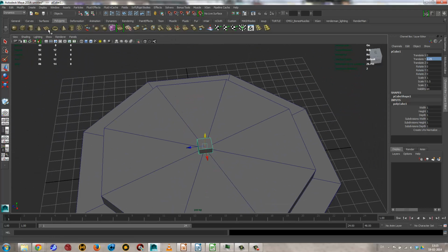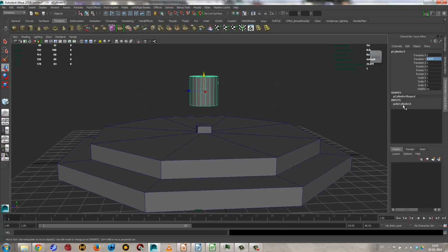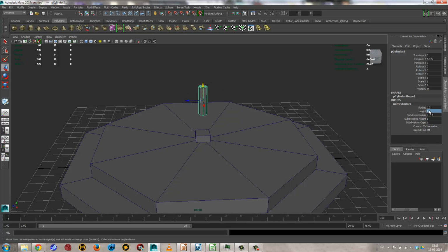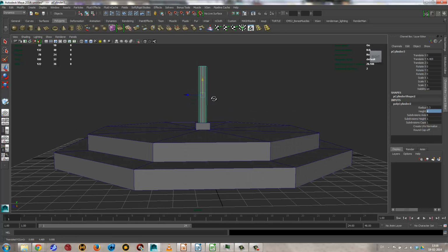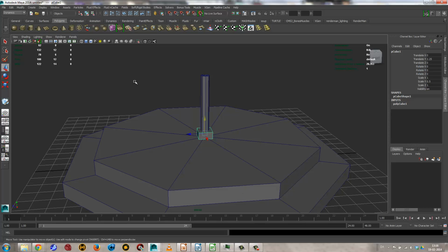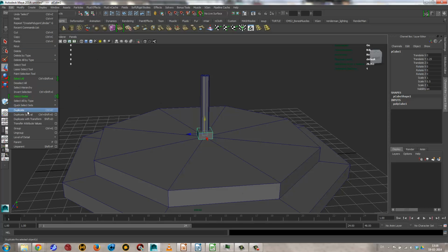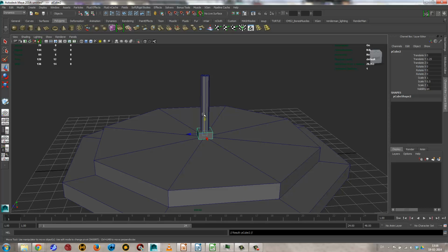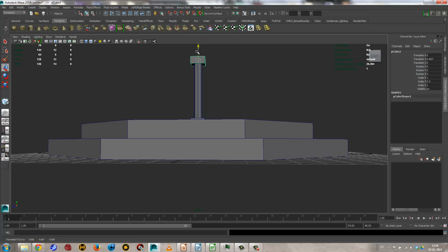Then on top of this, I want to create a cylinder, so I'll grab a cylinder. There we go. I'll just drag this up. This is slightly big. I'll make this 8 subdivision axes going around. I'll make the radius 0.6 maybe. Oh, that's too big. 0.3. Yes. Move this. Maybe make the height 4. And then I just need to place this. I'll just leave it like so. Grab this cube here and go to edit, duplicate, and that will create a copy right on top of the original. So just drag that up, place that up here, there.